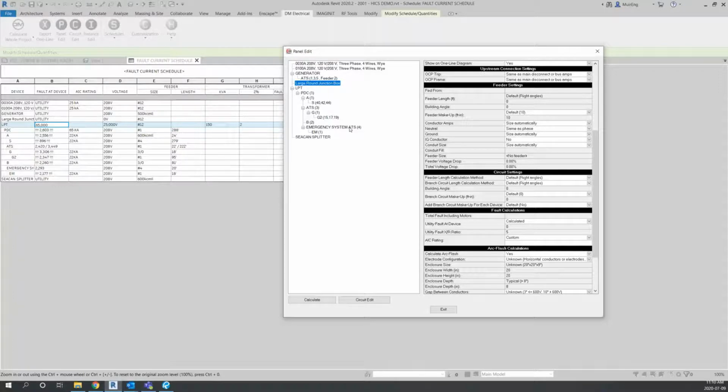just pointing out that not all electrical equipment is relevant to Design Master, or should even appear. So for the electrical equipment, there's an additional setting, which is a subtype or the category or something of that nature. There's panel board, switchboard, transformer. There's also, I think, electrical switch or something of that nature. If you change it to that type, it will disappear from this list. Okay, and I can just set those to switch, right?